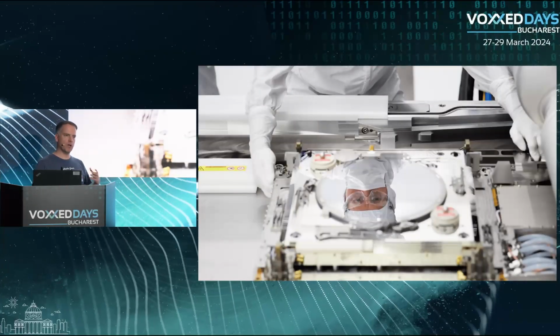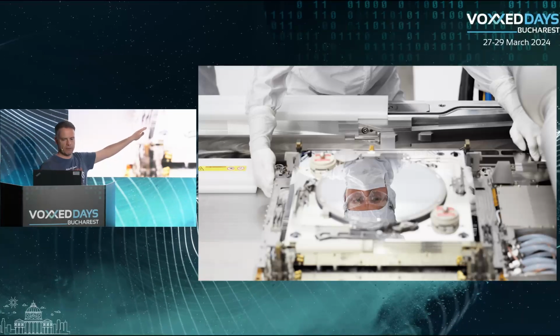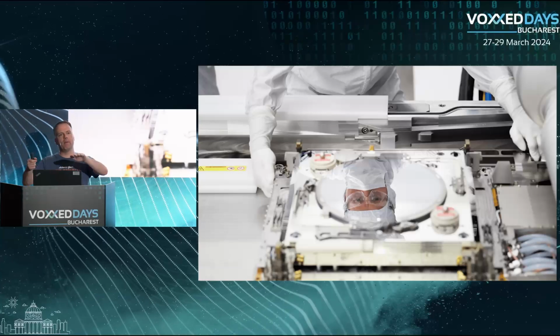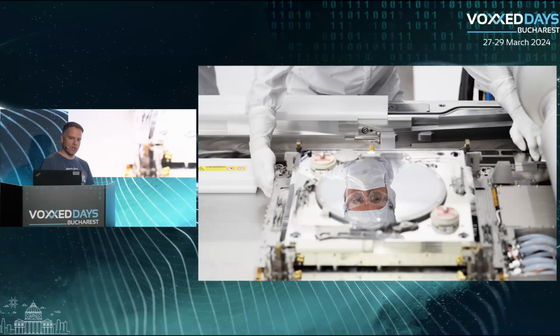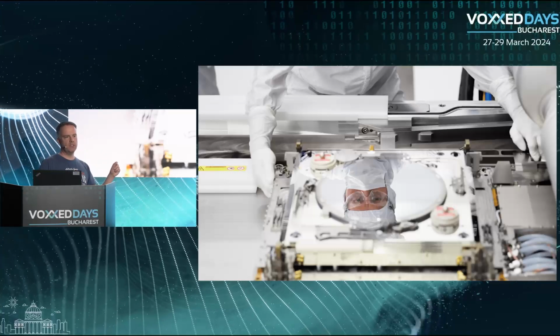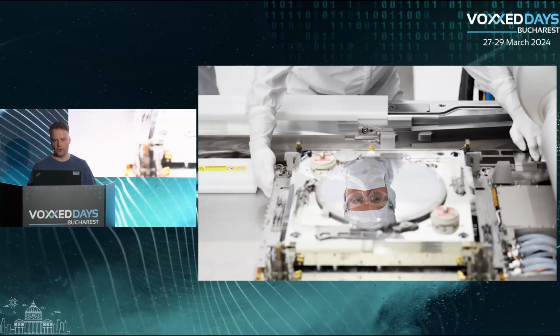So the wafer with the coating on it, the chemical, is put on a magnetically levitating wafer table. We cannot clamp it or something like that, because if we clamp it, it will bend and you will get more defect chips. So it's sort of hovering on top of this. And then what happens is we send EUV light to print the details in that chemical layer. And the next film will show you how that works.